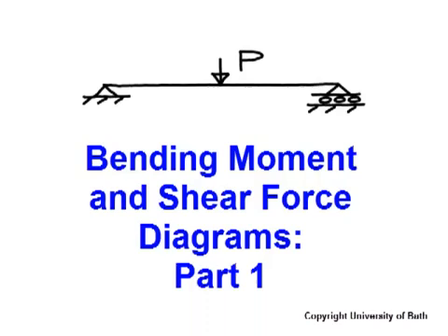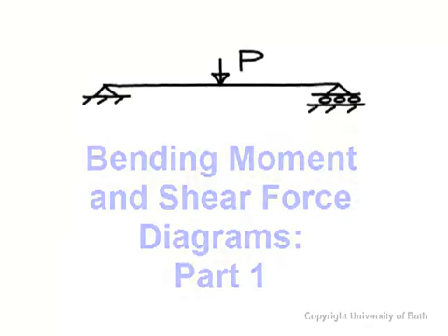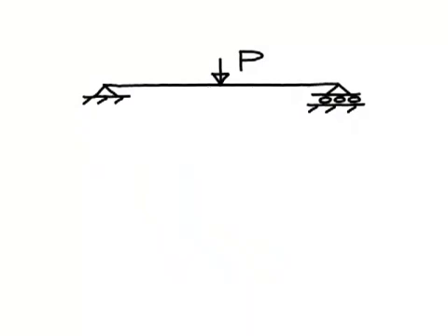Let's now start thinking about beams. In many ways they're similar to trusses, and we can analyse them in similar ways by using a free body diagram. So we start with a simply supported beam like this, with a load in the middle, and of course we can easily find the reactions. They're simply P upon 2 on the left-hand support and the right-hand support, both acting upwards.